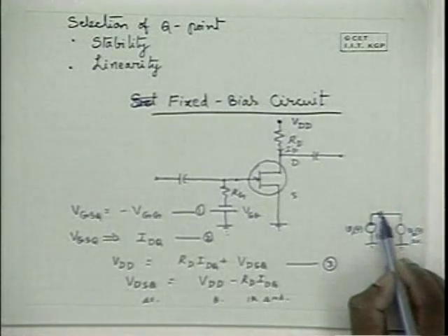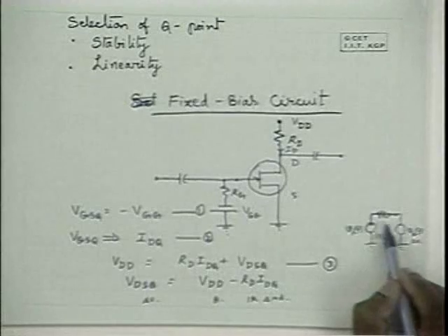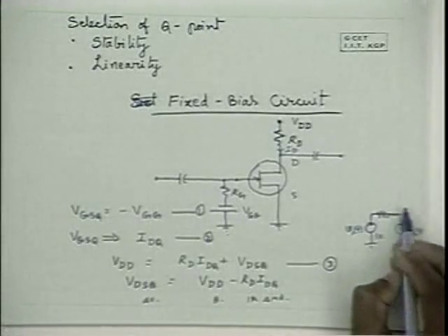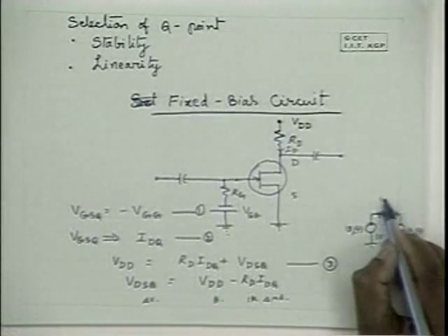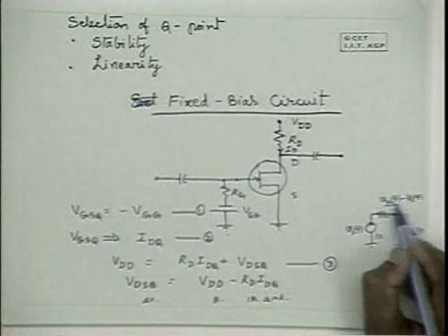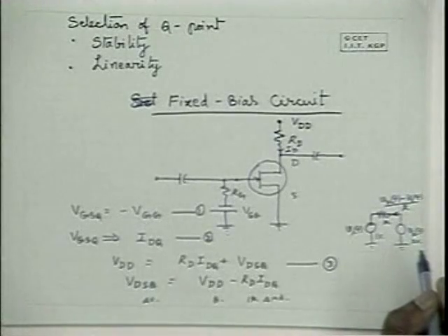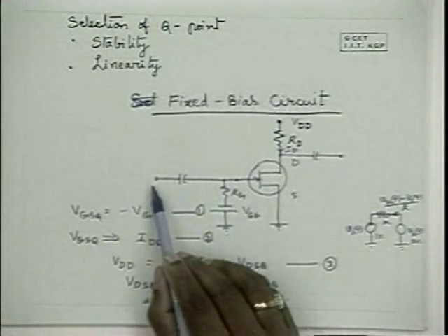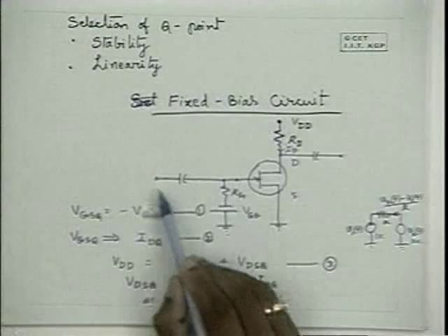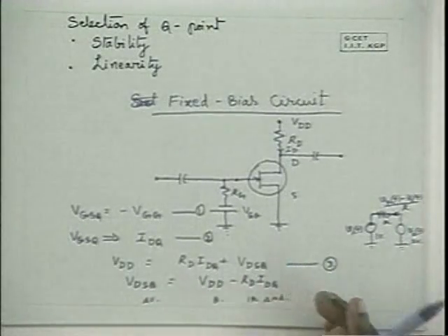Only when there is a resistance can you avoid shorting it, and this circuit now works with a current flowing in this direction as (V2(t) minus V1(t)) by the resistance R. Otherwise it gets shorted. Now to prevent the shorting of the input signal into VGG, this RG is provided here.